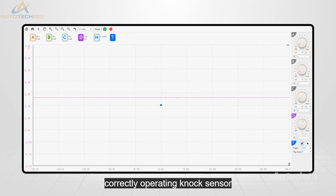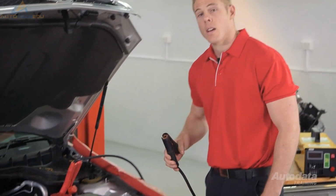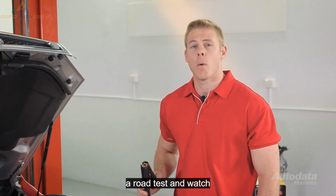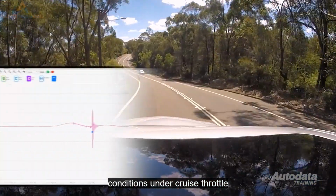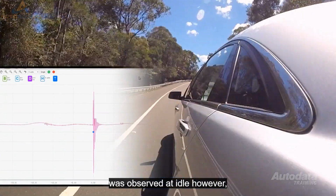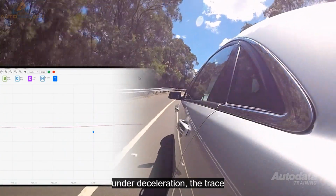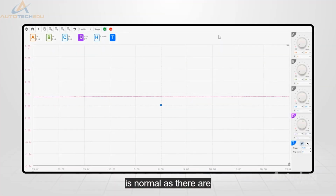This is what a correctly operating NOx sensor trace looks like at idle. Let's take this vehicle for a road test and watch the trace under different load conditions. Under cruise throttle, we can see the trace is very similar to what was observed at idle. However, under deceleration, the trace oscillations are reduced. This is normal, as there are no combustion events due to injector cut under these conditions.